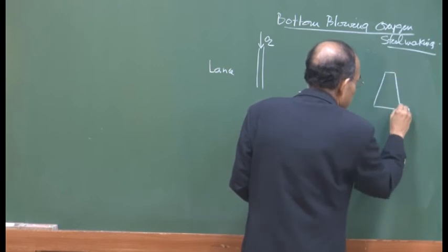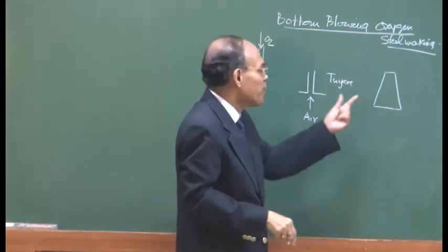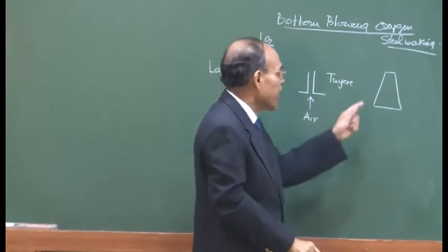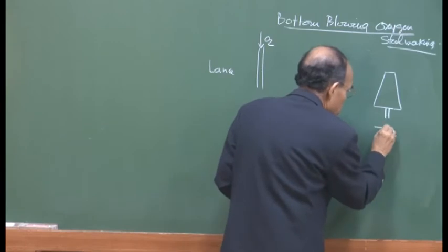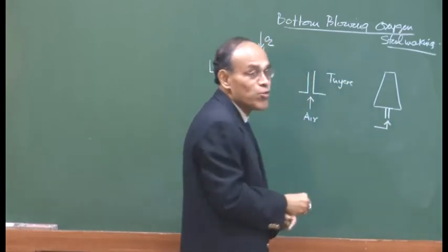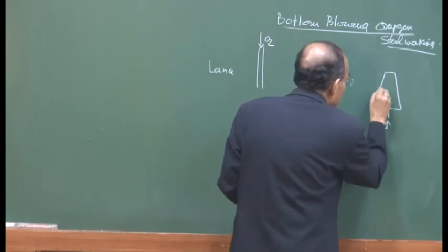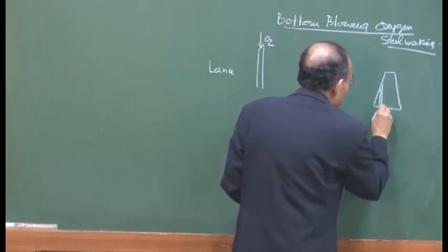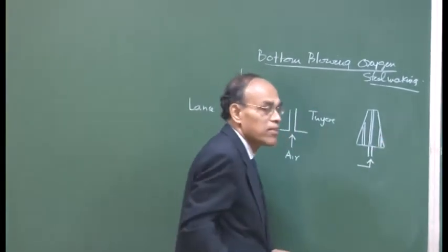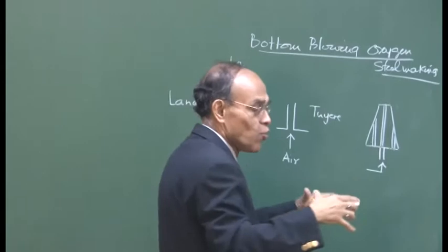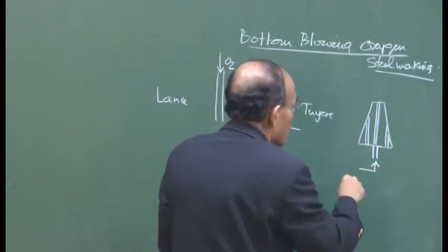It is a ceramic artifact. It could have channels; it is a prefabricated structure, and there could be a number of pores, and there is a pipe here through which the gas is introduced, and the gas is released from all those pores. Directional porous plugs are also there. So, there are innumerable channels. If you look at the cross section, it looks like the frustum of a cone, a portion of a cone.